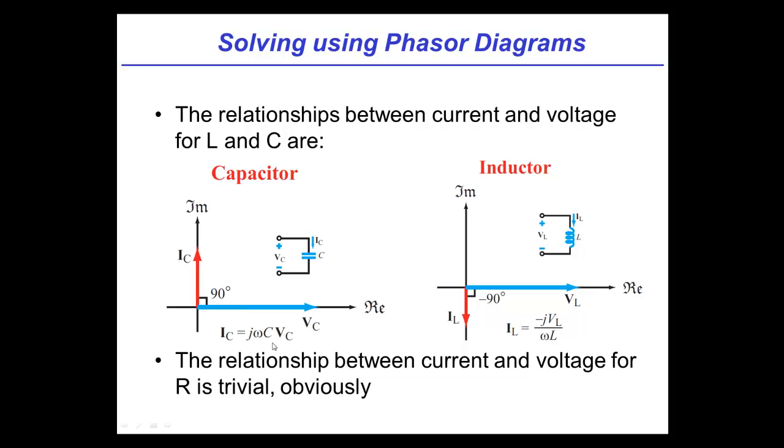Exactly. Now, for an arbitrary case where VC might have an imaginary component and is not perfectly horizontal, I will still keep that 90-degree phase shift. So if VC is up here, maybe at a 45-degree angle, where would your I be? Your I would be 90 degrees leading that, so it would be in the second quadrant. Right. And this is always true. This is a really neat little graphical thing to see. It is always true that the current in a capacitor and the voltage across the capacitor have this 90-degree phase shift, in this particular leading and lagging configuration, no matter what the actual value is.